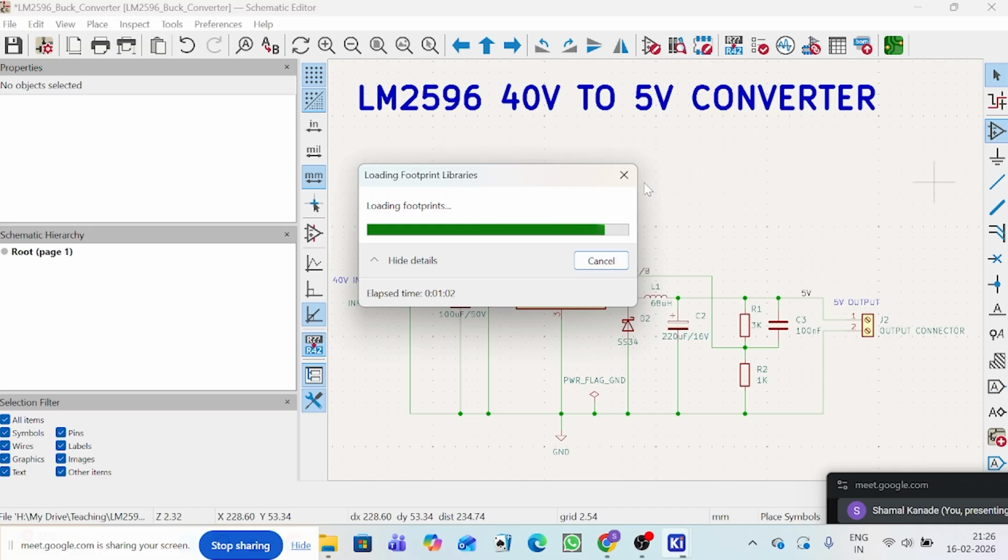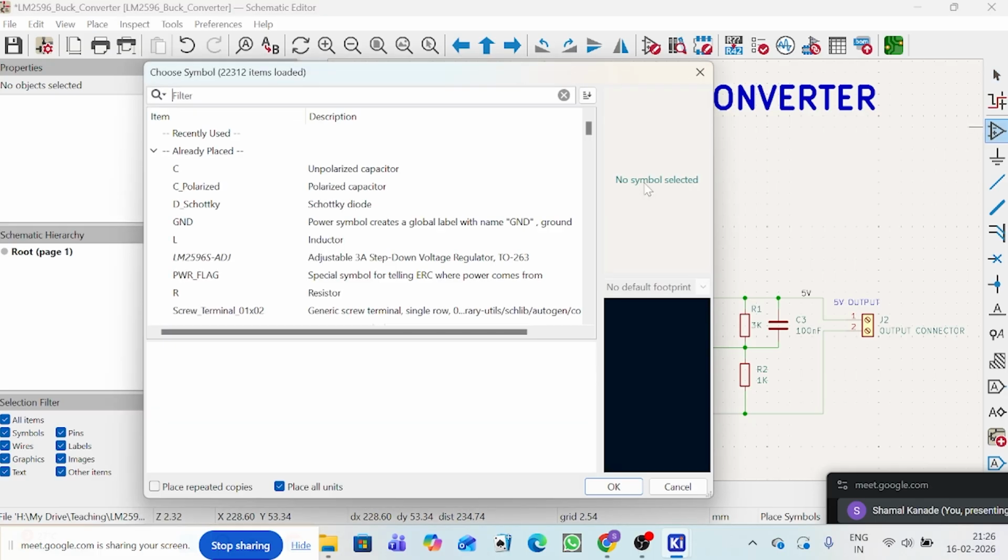How to draw a custom library of resistor, inductor, diode? Actually, there is a different method also available. There are sites like SnapEDA, DigiKey, Mouser where these symbols and footprints are available. You can just download and use them if you don't want to create one. I will also show how we download it and use it.